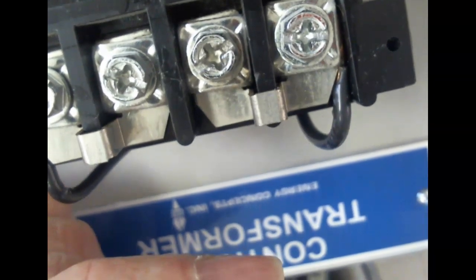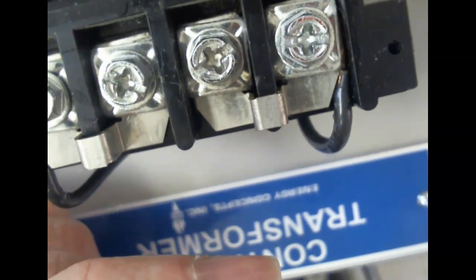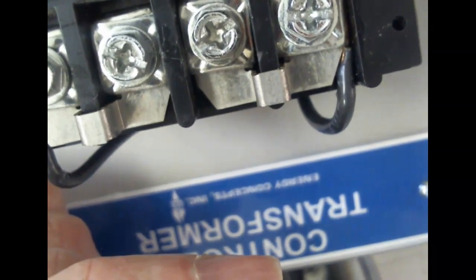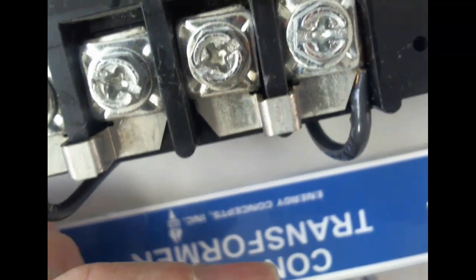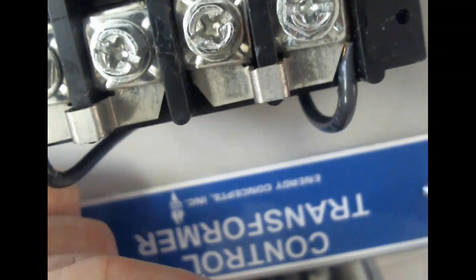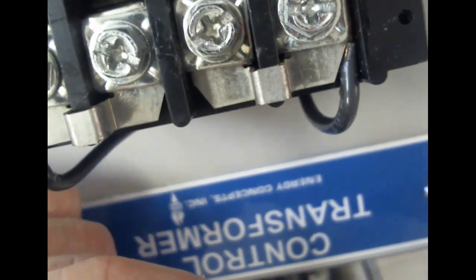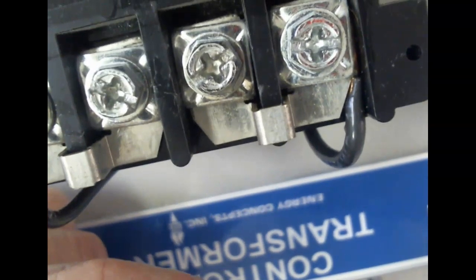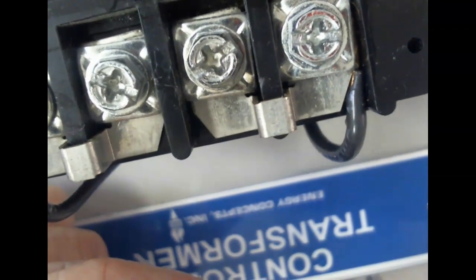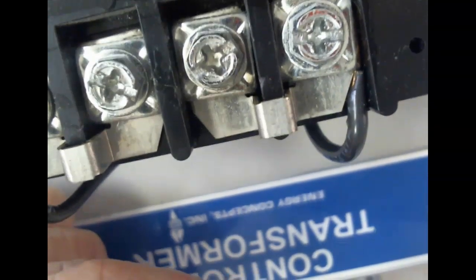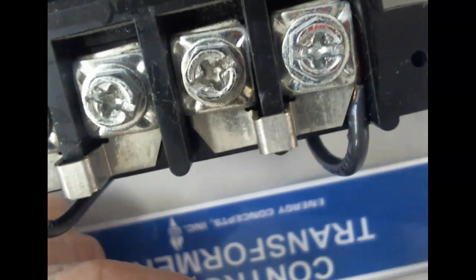You understand? The source. So on sources, the higher I can make the voltage, the less current's required to produce the power in the load. The voltage required by the load dictates what you have to do with your transformer. So if you've got a load rated at 120 volts, by George, you're going to have to set your transformer up to get 120 volts, right? So the source is not dealing with voltage and current, even though they are in play. The source is dealing with how much power I've got to get out to that load, and you have to get that power at a certain voltage.